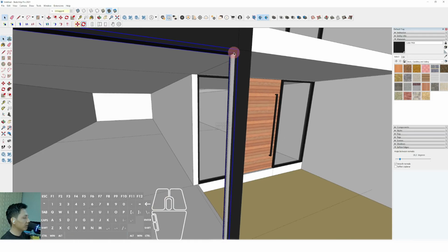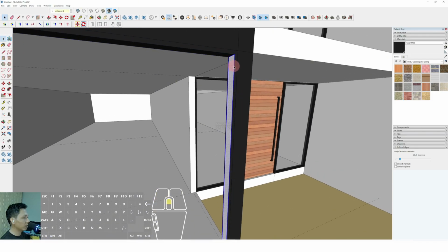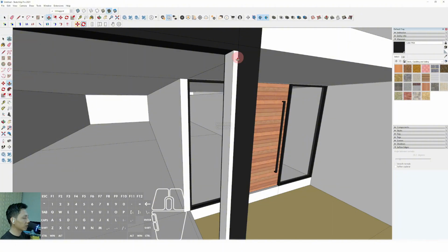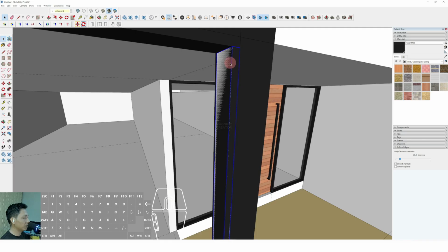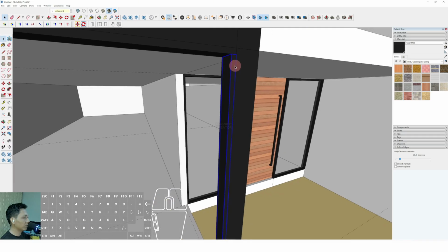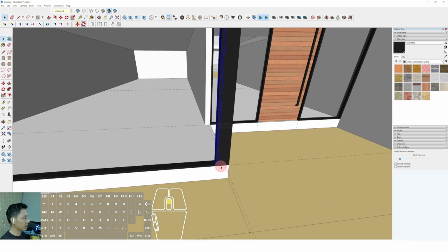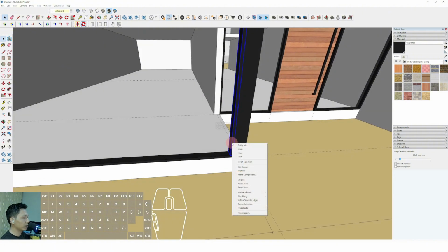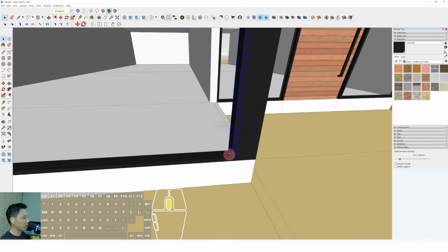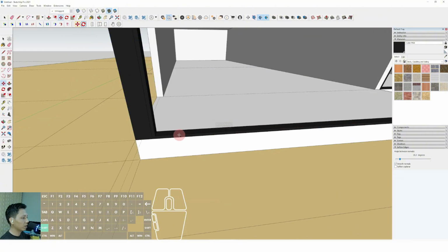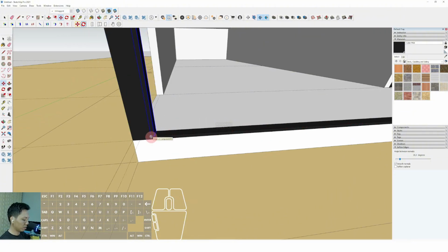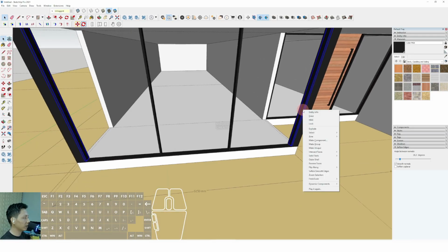Okay, we can draw the rectangle and set the thickness of this rectangle, and triple click, right click, make group, and assign the frame material. Okay, we can right click and make component, create. Then we can select move, tap control on our keyboard and click from this point until this point. Then we can type 3/ and enter. Then we can click this frame, right click, and erase.